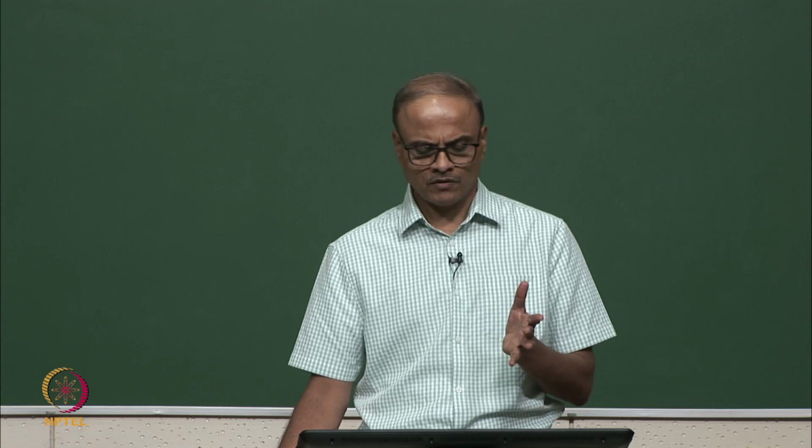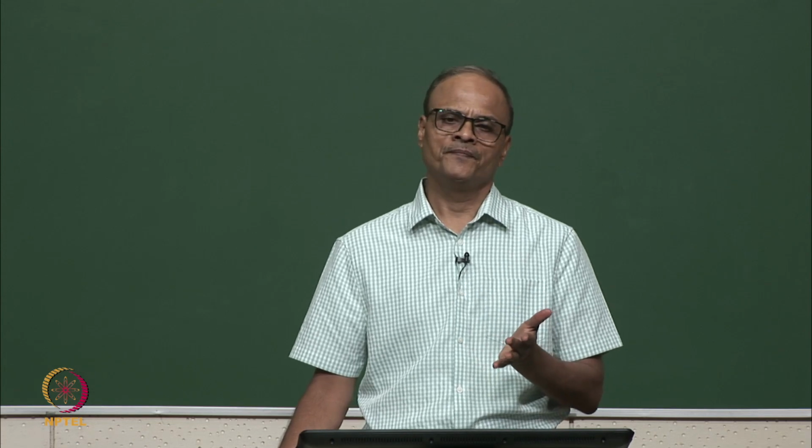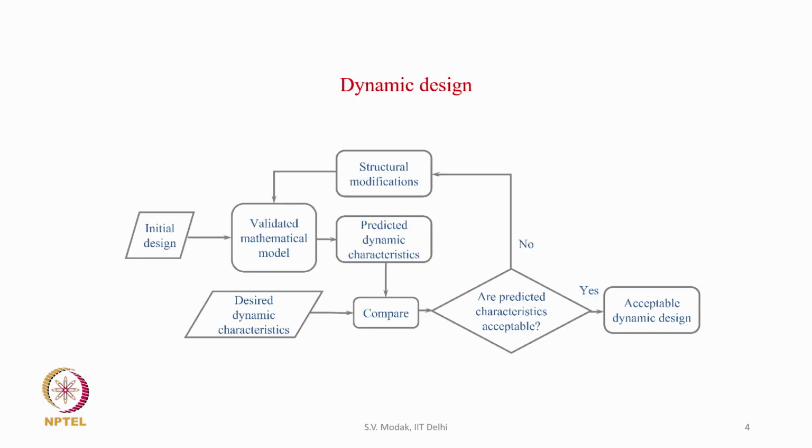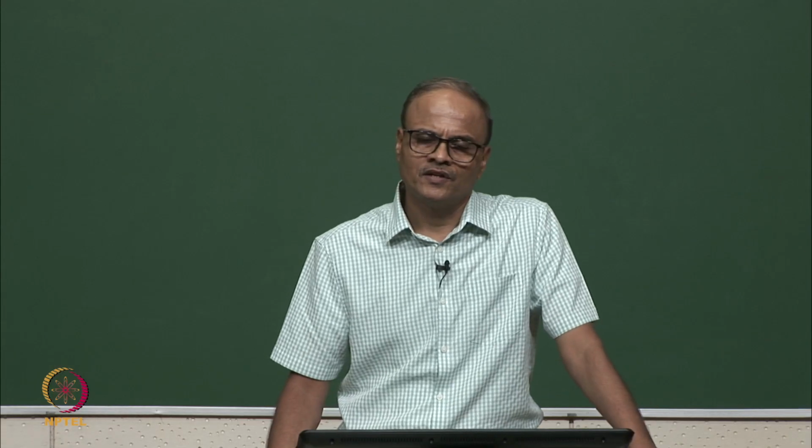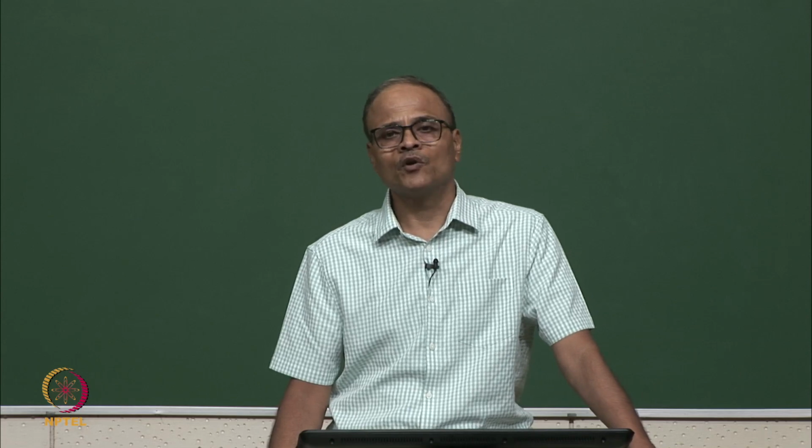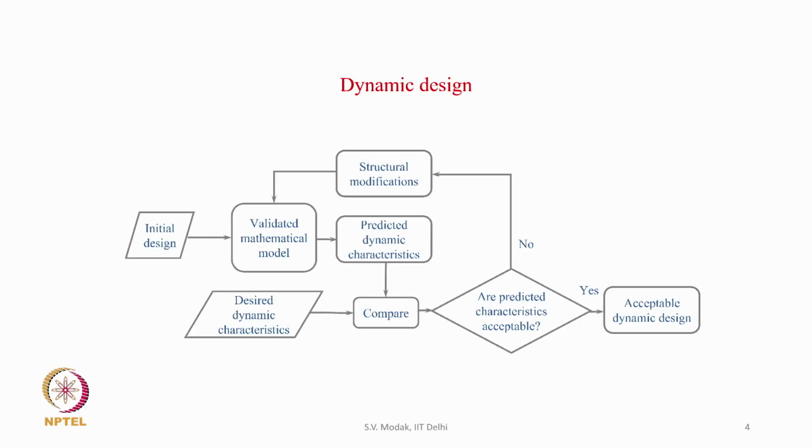One could be a test based approach, other could be a model based approach. So, in the test based approach, whatever modifications are incorporated, they are physically incorporated into a prototype based on the initial design, and then the dynamic tests are carried out to see whether the dynamic design requirements are satisfied or not. But this would require a large number of physical tests, and it is going to be pretty uneconomical and time consuming.